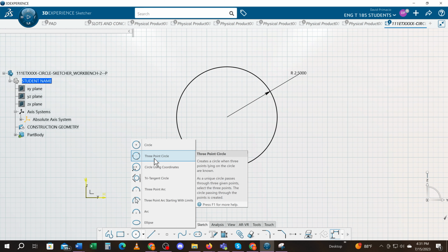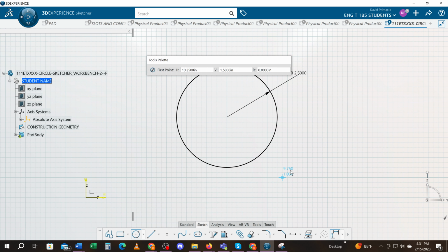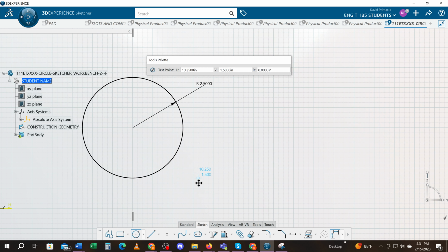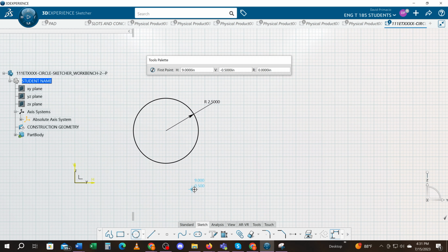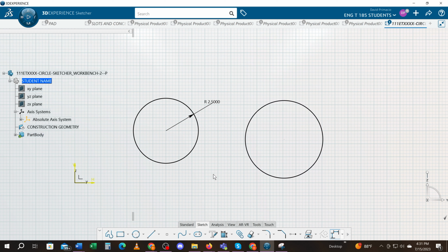There's also 3 points. If I slide over here, I can create another circle. Let's go. I like to create them counterclockwise, so if I start here on a grid, I can click and drag this up, click, and then wherever I click the 3rd point, it uses that to define the radius of that next circle. Whoops. Again, one more time, I'll hit undo.